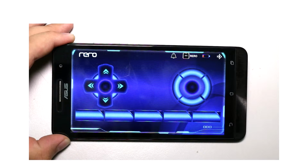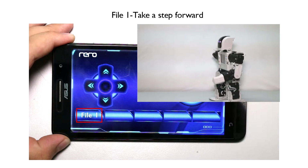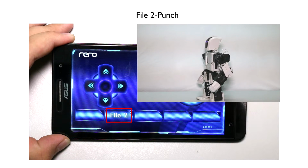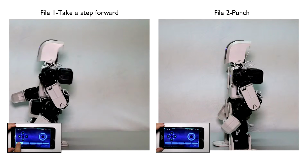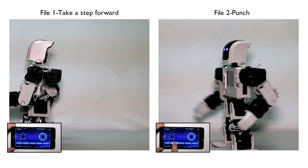For example, I will make the first motion file. File 1 contains the motion: take a step forward. File 2 is the motion: punch. So now if I press the first button, the robot will move forward. If I press the second button, the robot punches.